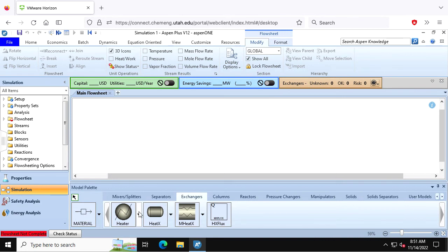So now you're learning how much heat transfer area do you need, right? And maybe you come up with a heat exchanger that needs 15 square meters of heat transfer area to achieve the level of heat exchange that you want. But you probably haven't gotten into, okay, what does that look like? Maybe you've gotten to how many tubes, what the shape of those tubes is? How many passes are there? Does it have a floating head? Is the shell side distribution, does it come up or does it come down? Does it split? All that kind of stuff you can work out in ASPEN.